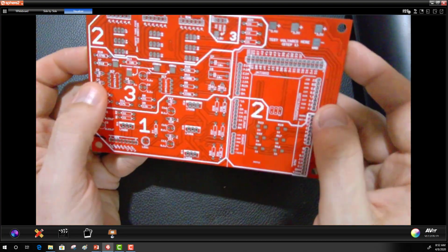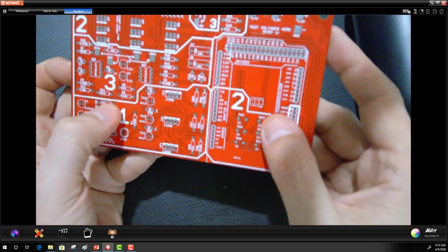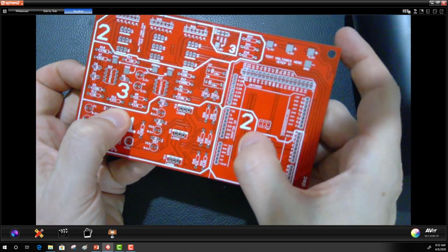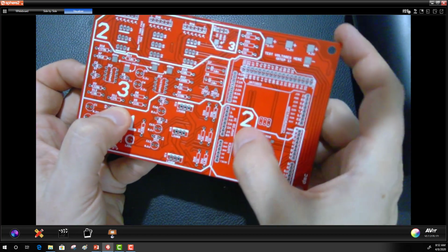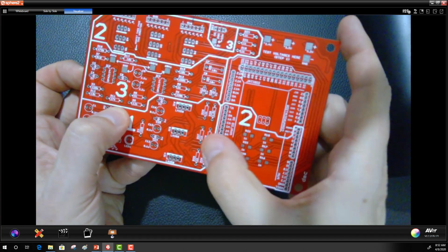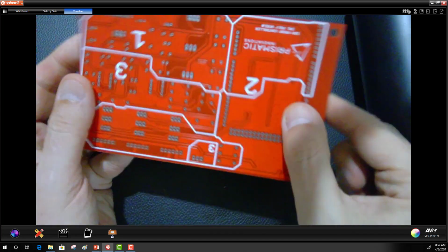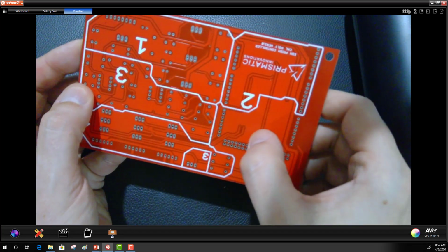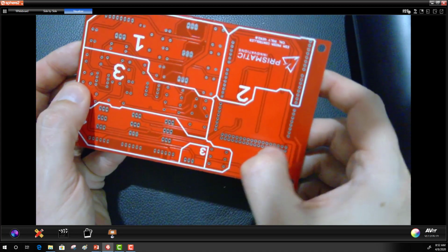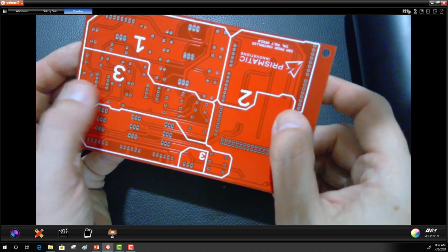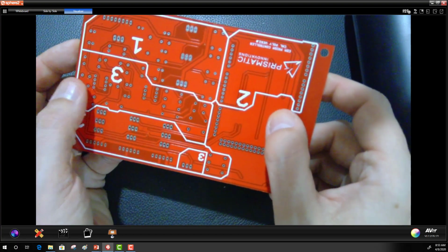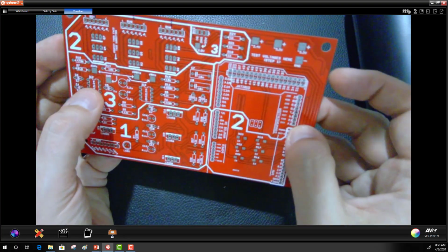This IME 156 board here. See these patches of copper that are adjacent to the traces. See the lines of the traces, but then when you don't have traces, there's these big patches of copper. See on both sides here, there's a trace, and surrounding the trace on both sides is a big patch of copper. Those patches of copper, that's what's referred to as the copper pour. And again, they're there to help dissipate heat.